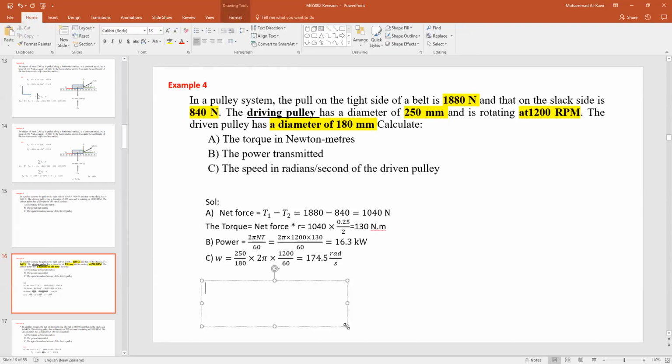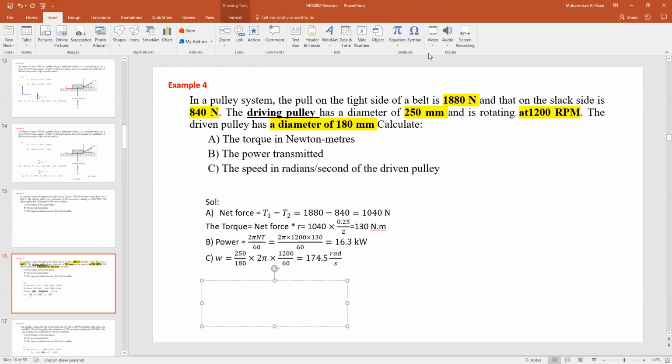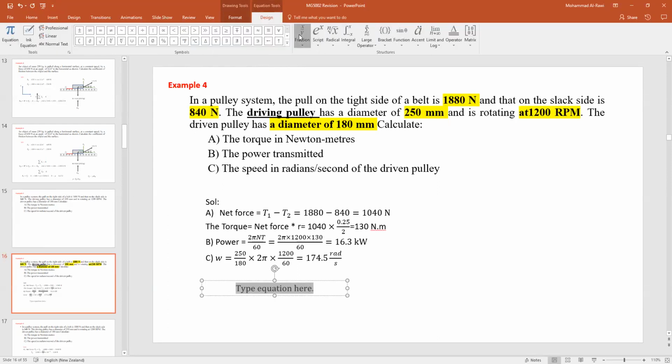So, okay. To find the speed, I'll write this equation here. So what do you have? You have the ratio: n speed divided by... So which speed is this? This represents the speed of the bigger pulley. So it will be 1200 RPM, divided by n, which is the speed for the smaller one that we don't know. This is in case I'm getting it in revolutions per minute.